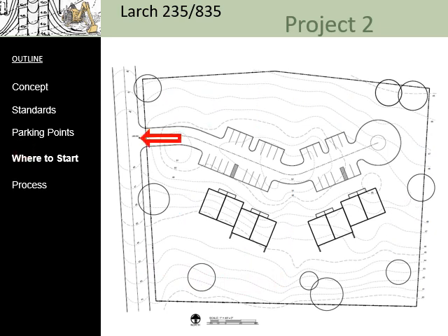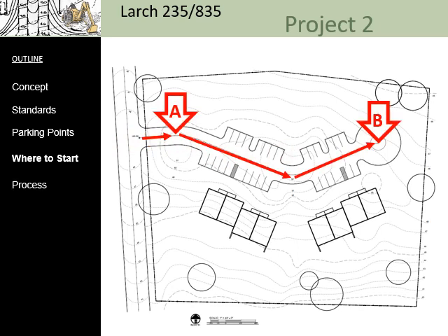So as you've also learned from previous assignments, once you have those restraints figured out, you always want to start with what's known. And what's known in this case is the elevation where this driveway meets the road. So you will always start from there and work your way up the parking lot. And in this assignment, we've done a large portion of that for you because we've told you what the elevation has to be at A. We've told you what the elevation has to be at B.